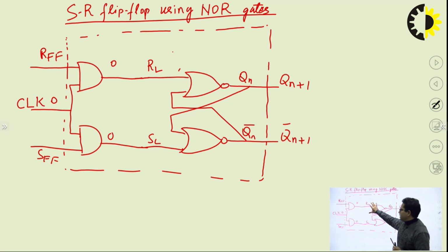We have understood in the last class that this NOR latch considers 1 as an input. So for the input 0 0, it is still waiting for the input to be given, which means that it will hold the past value. It will not change its past value.